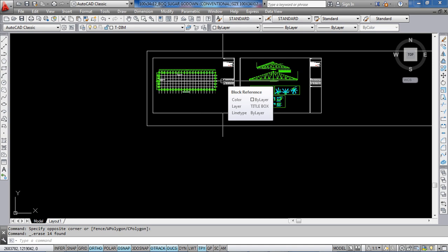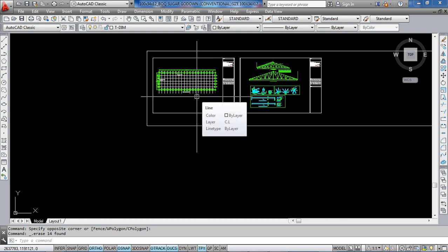So first of all, we will create a DXF file. But before creating a DXF file, we have to make a DWG file of the required truss. As this drawing has a different layer, we will not use any existing layer. We will insert a new layer for making the line diagram of truss.